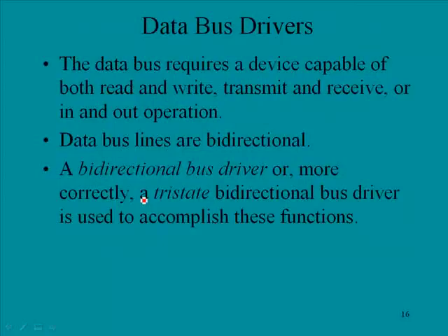Okay. The data bus drivers. The data bus requires a device capable of both read and write, transmit and receive, or in and out operation. Data bus lines are bidirectional. A bidirectional bus driver, or more correctly, a TriState bidirectional bus driver, is used to accomplish these functions.